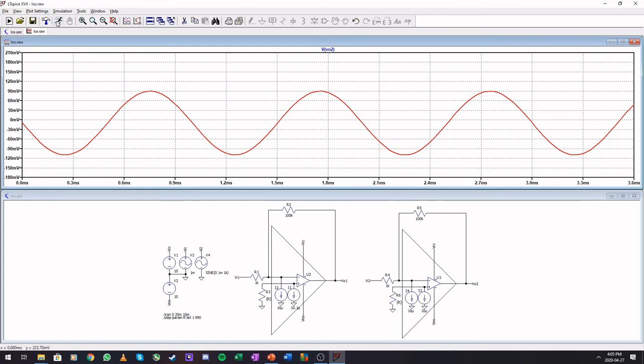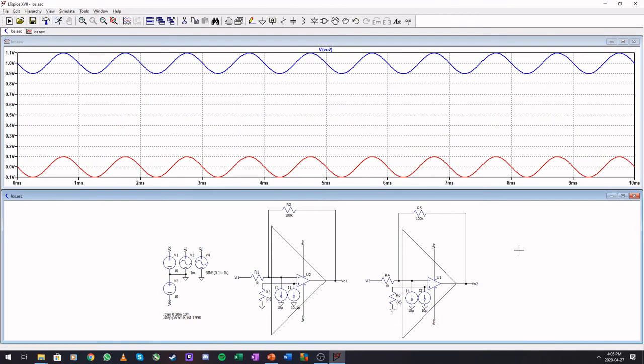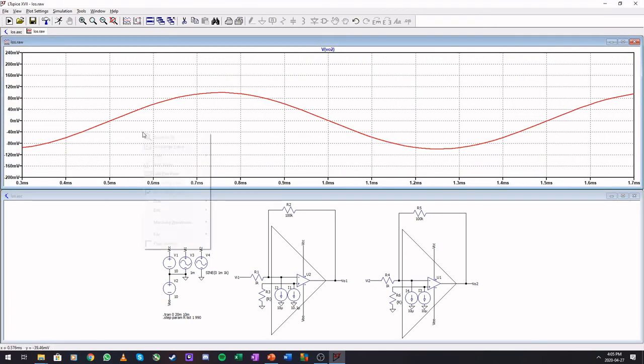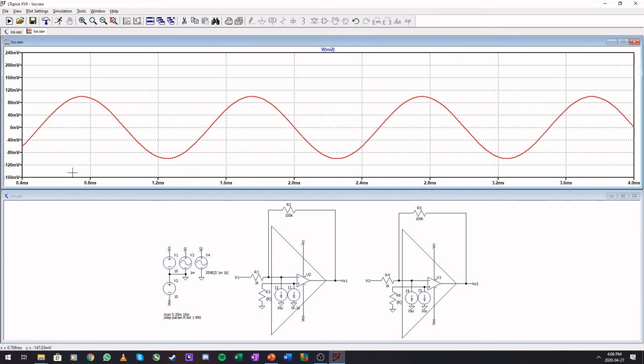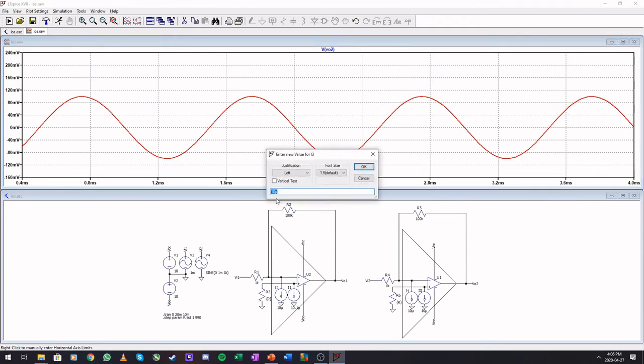So if we fix that, take a bit more signal, you will see that these circuits are now more balanced. Adding this resistor removes the DC offset, and we will only see the effect of the imbalance between these two current sources.